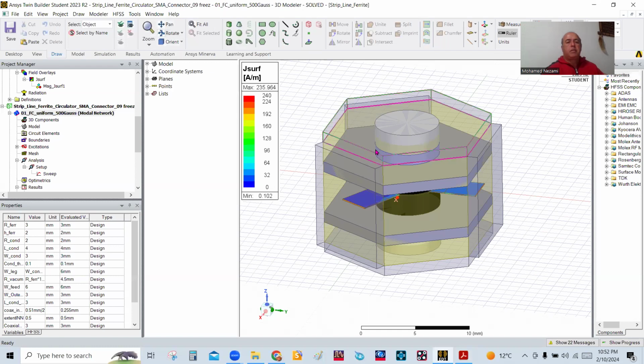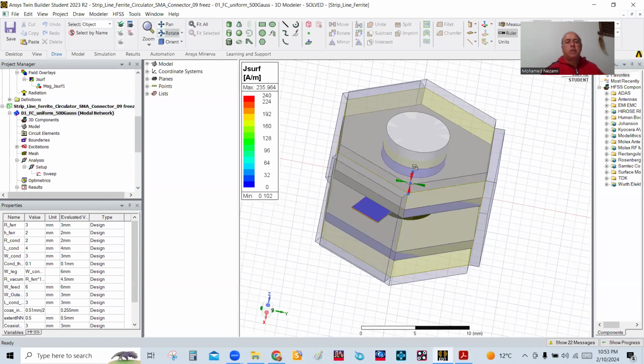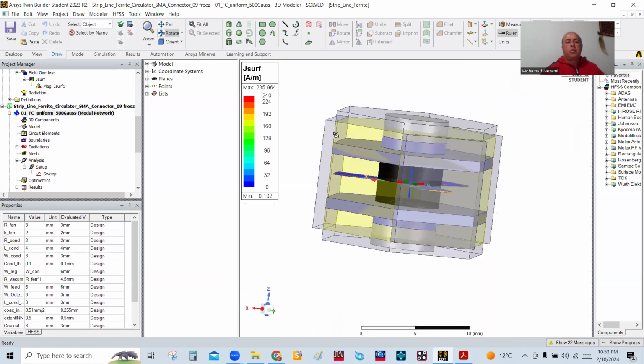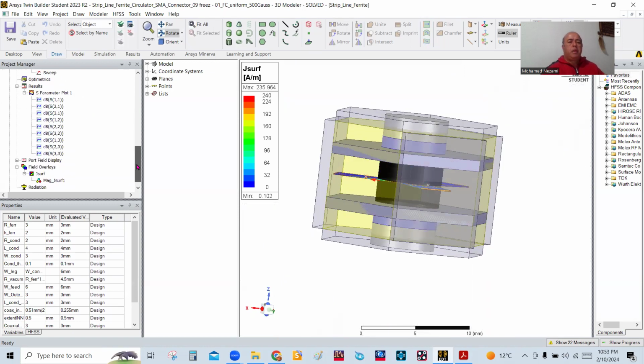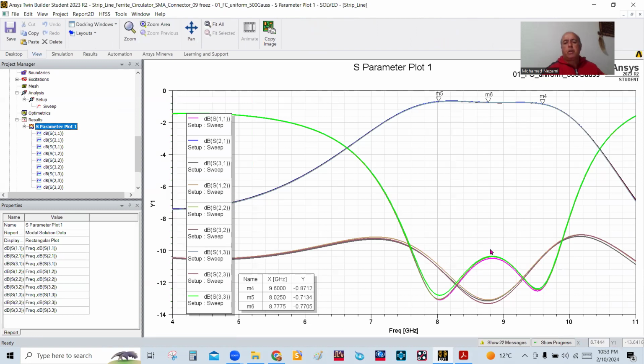So what I did last time is I took one of the circulators that I designed, which is a stripline circulator, and it's right here. So let's just go through the dissection of this. And this one here, of course, I tuned it a little bit further. So it's designed at about 8.75 gigahertz center frequency, okay? And it operates between 8.7 to 9.6.